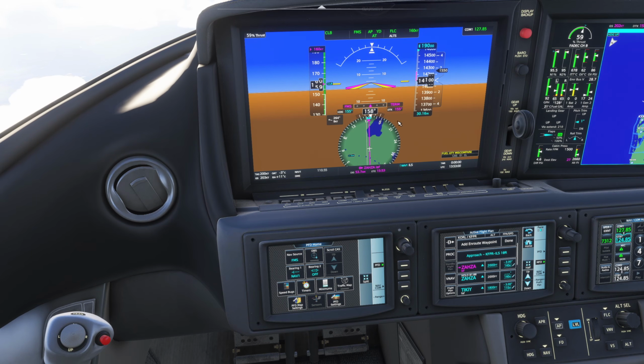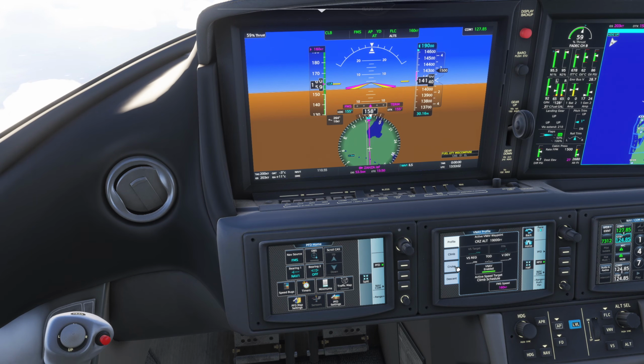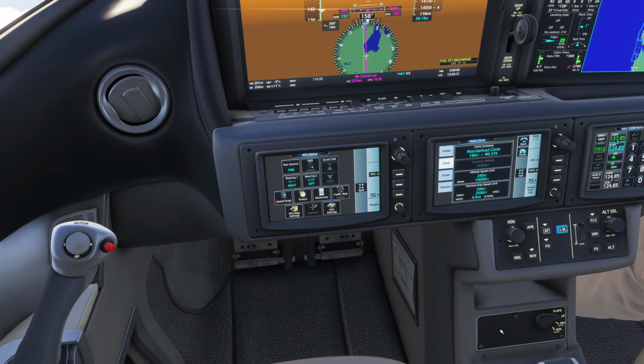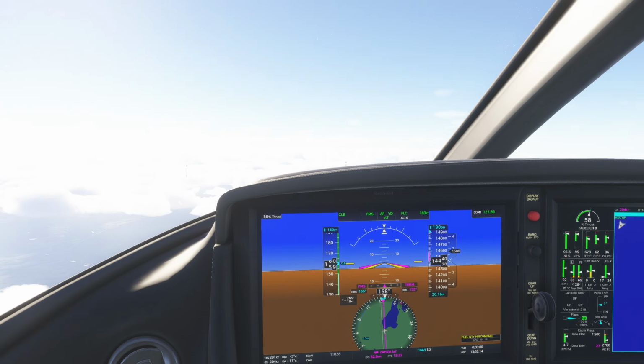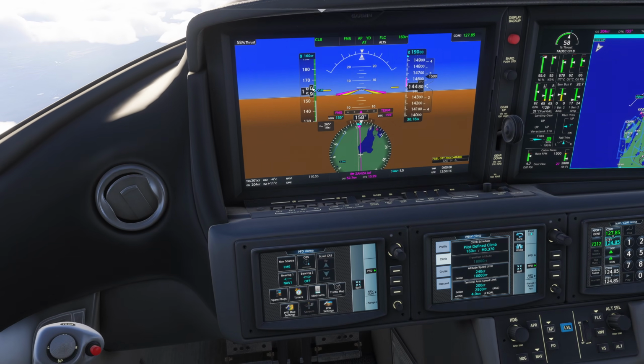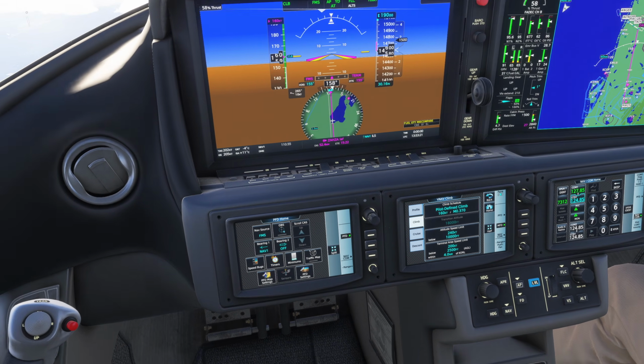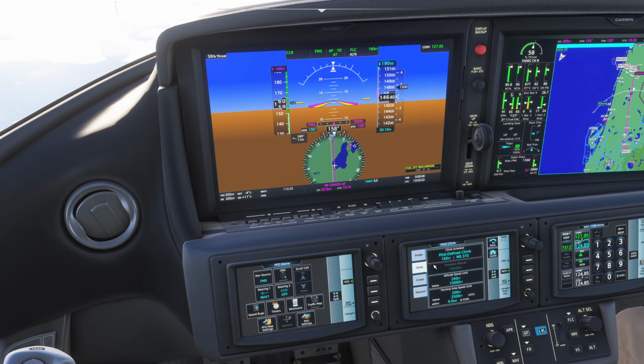and the plane is still targeting what we've set in the climb speed here, 160 knots, and that's why it's in magenta. Magenta is the FMS color that the plane is targeting, and the blue cyan color is what we're manually targeting. Okay, so 160 is what we manually set the bug to. Magenta is what the plane has calculated, that we've programmed into the plane to hold to.